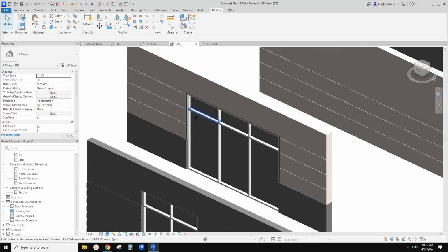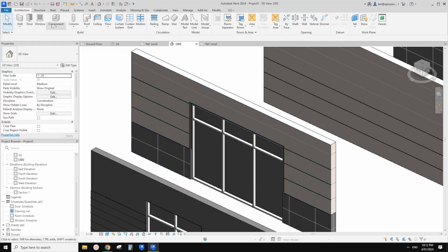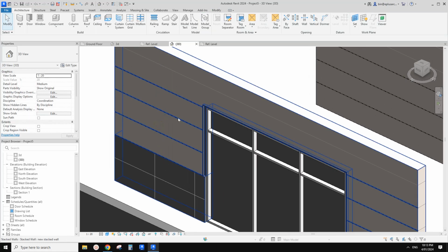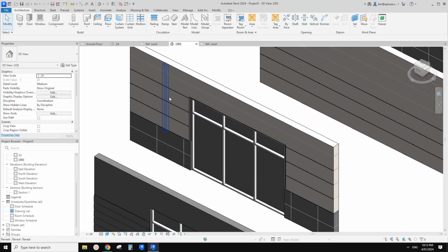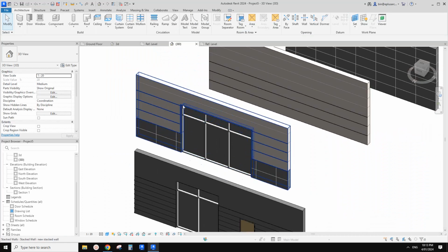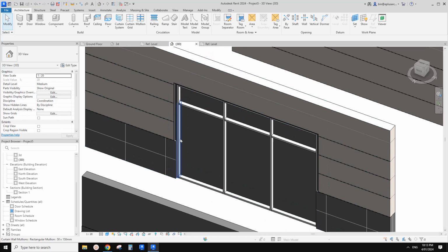You can also use reveal. For example, you can create a wall, just create a reveal, right? Use the proper profile, and you can just place it vertically, or where is it? Sorry about that. It's not cutting the wall, it looks like. Anyway, you can do it manually, but it's easier to do it with a modeling place because you can just create this in one place.